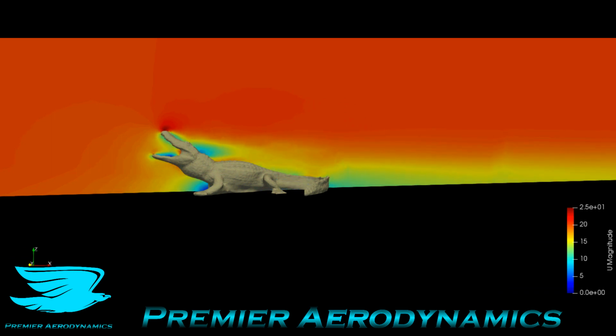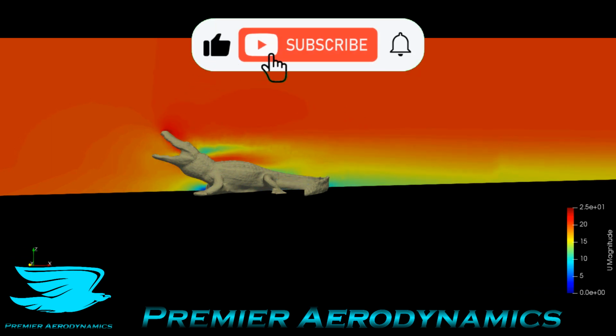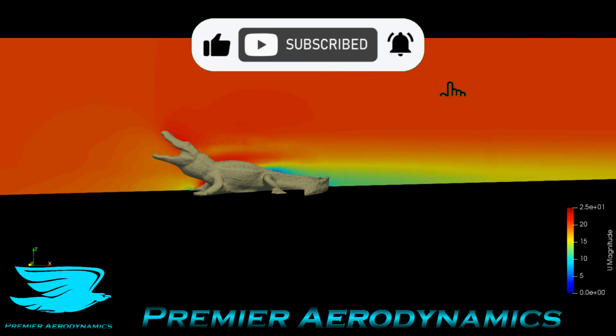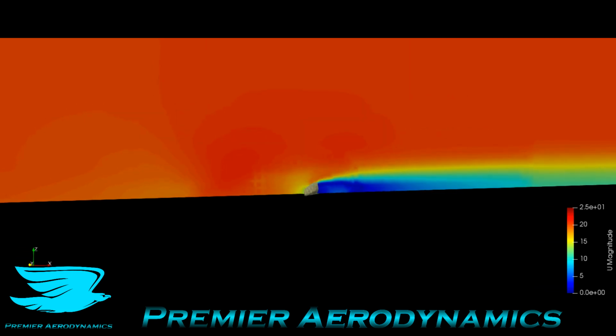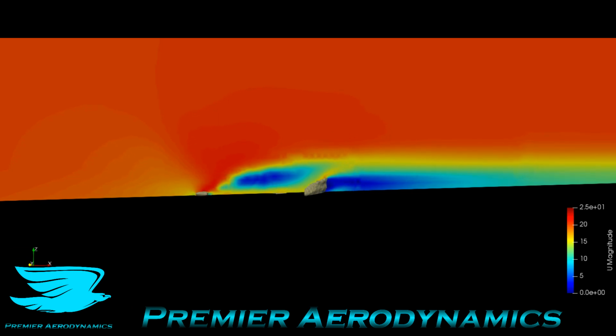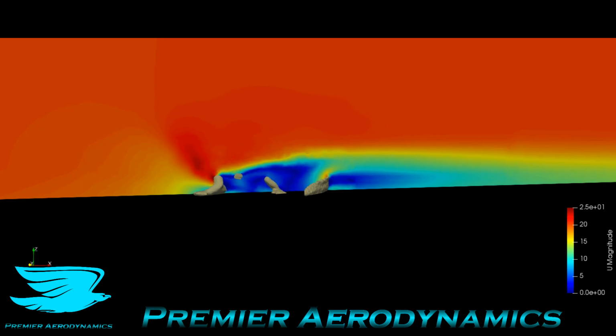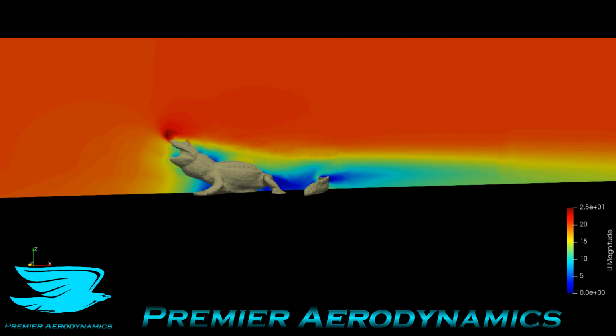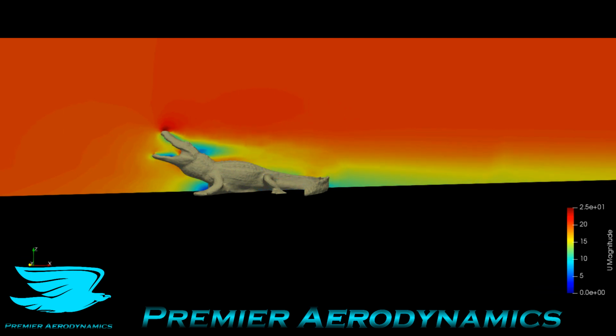So the tail, how it's curled, is not aerodynamic, but the head itself, how it's pointed up at an angle, you can see that the flow actually stays attached fairly well. There are only some very slow-moving fluid areas where there are indentations, effectively where the neck is. And then between the nose and the eyes, there's a little bit of a trough. And then between the eyes and the neck there's another little bump. So those regions are slow-moving fluid, but the rest of it's quite well attached.